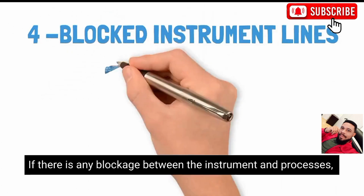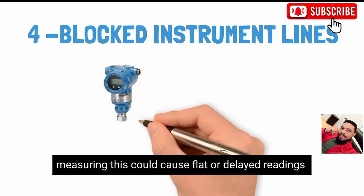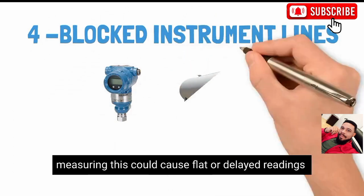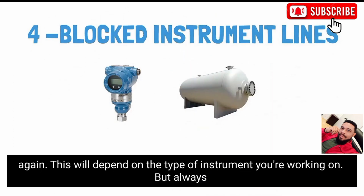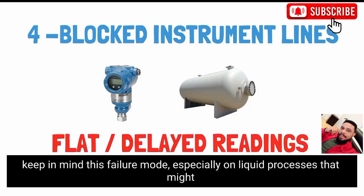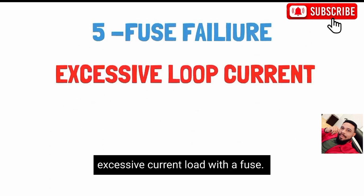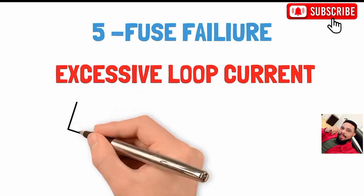Blocked instrument impulse lines. If there is any blockage between the instrument and process, measuring this could cause flat or delayed readings. Again, this will depend on the type of instrument you are working on, but always keep in mind this failure mode, especially on liquid processes, which could contain particulates. Fuse failures. Most loops provide protection from short circuits or excessive current load with a fuse.